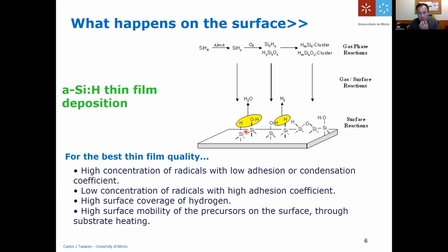You'll see that it's really important, if you want to have hydrogenated silicon, to provide these molecules that have the radicals that will make the bonding between silicon and hydrogen, and also silicon with OH groups. Afterwards, you can remove part of this excessive hydrogen and oxygen, because these radicals that you see here, for example a hydrogen radical and an OH radical, can just form water and be taken away.